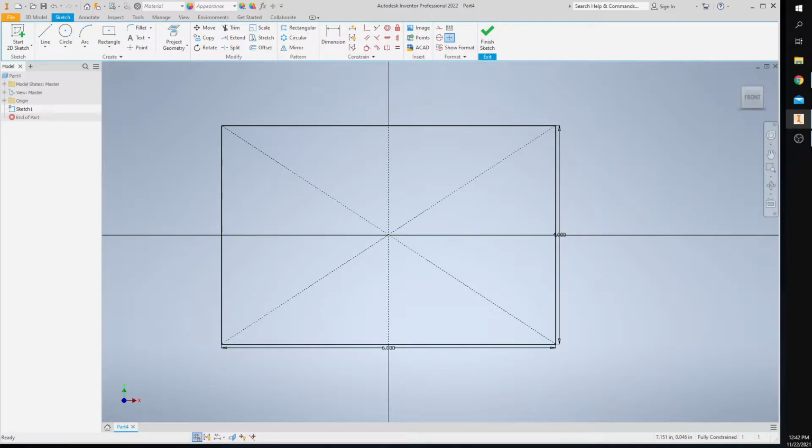All right, so now we are in step 5. Add 3 polygons inside your sketch rectangle. And then it starts off with a circumscribed pentagon using a radius of 0.35 inches. Okay, so first I'm going to put down the polygon sketches. And then after I put down all 3, I'm going to go ahead and give them dimensions.